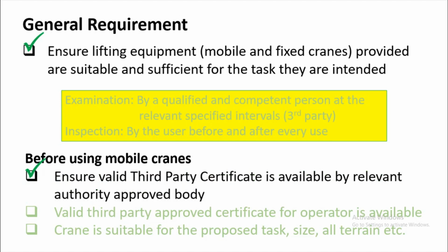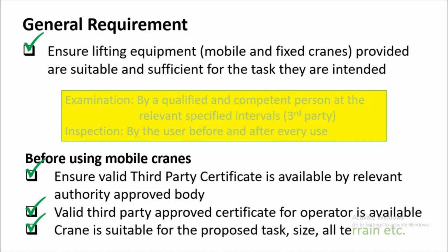Before using mobile cranes, ensure a valid third party certificate is available from a relevant authority approved body. A valid third-party approved certificate for operators is available on the site. The crane is suitable for the proposed task, size, all-terrain, etc.